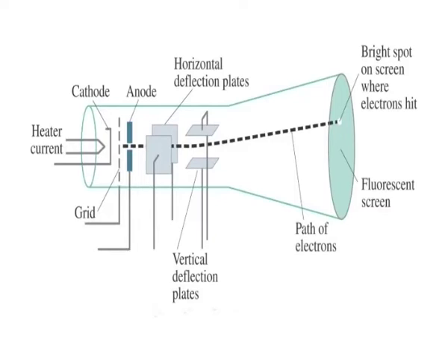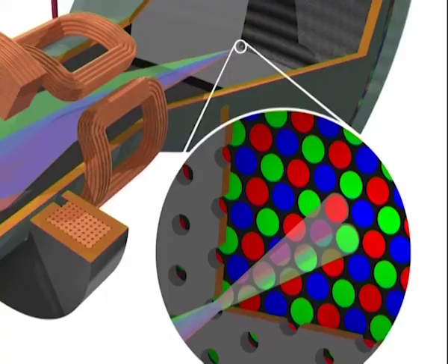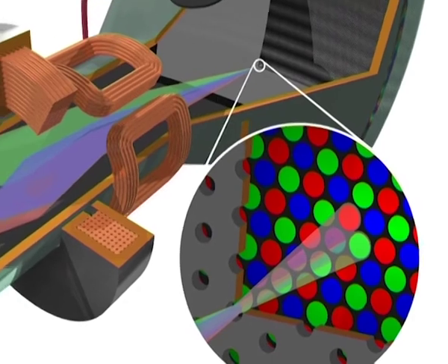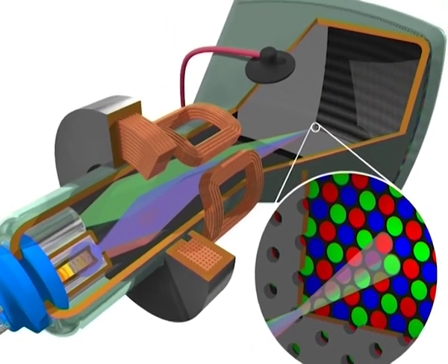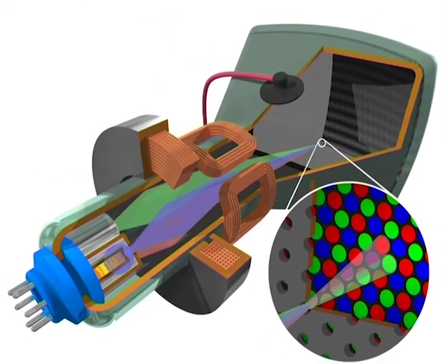Displays. Colored phosphors on a cathode ray tube screen glow red, green or blue when they are energized by an electronic beam. Because the intensity of the beam varies as it moves across the screen, some colors glow brighter than others. Finely tuned magnets around the picture tube aim the electrons precisely onto the phosphor screen, while the intensity of the beam is varied according to the video signal.